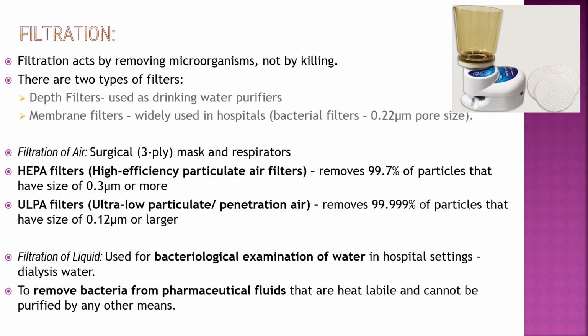Filtration of air: surgical three-ply masks and respirators. HEPA filters, high efficiency particulate air filters, remove 99.97% of particles that are 0.3 micrometer or more in size. ULPA filters, ultra low particulate penetration air filters, remove 99.999% of particles that are 0.12 micrometer or larger.